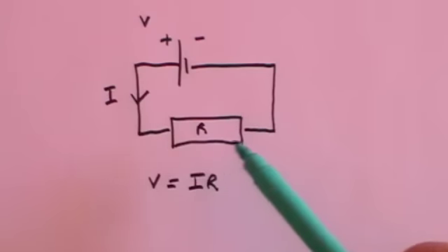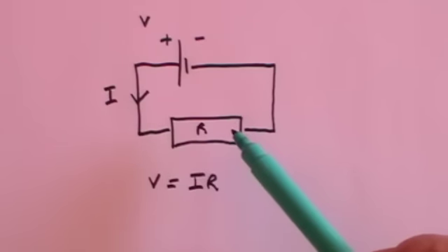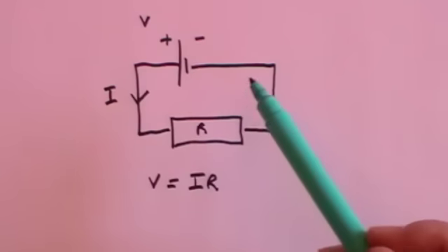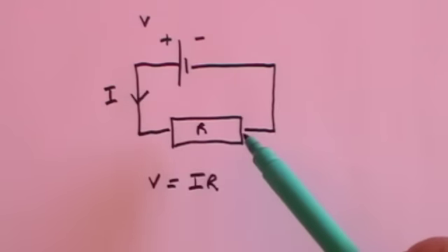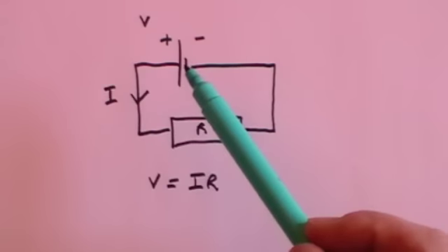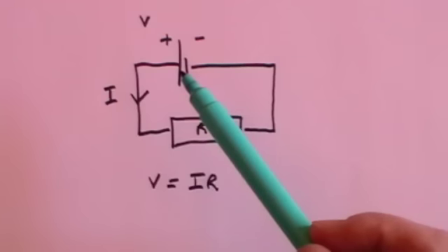All of the real resistance in the circuit is in the resistor here. So no great harm done by assuming that there's no resistance associated with the wire that is connecting the battery to the resistance. But we've also made another assumption, and that assumption is that there is no resistance in the battery itself, and that is usually wrong.